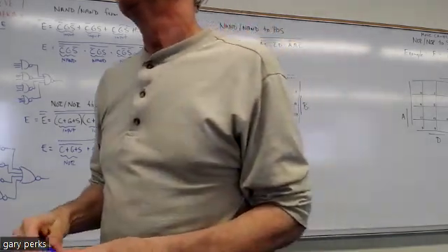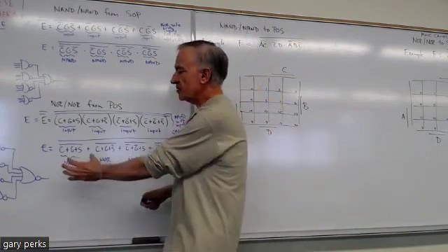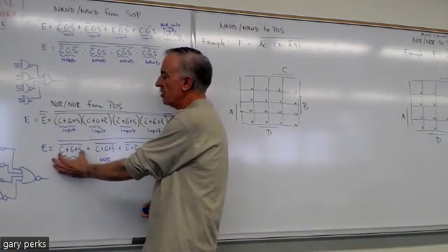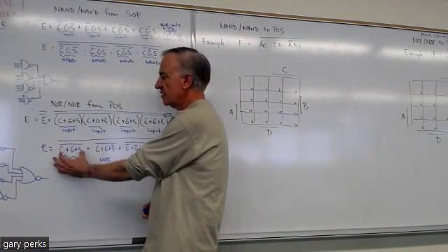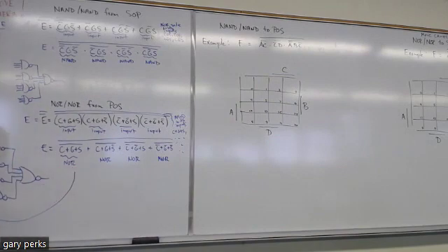How would you code all the NOTs, or would you simplify that part? Are you talking about these terms here? Yeah, because would you just do NOT C? Well, in Verilog, to do this term here, I would just put in parentheses C ORed with G ORed with S, and then you put the tilde outside the parentheses. That would give you this term.